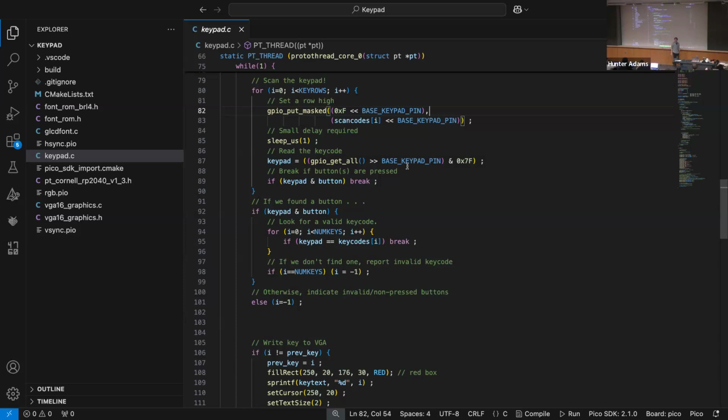So those of you that have run the keypad demo code, you will know that all that keypad demo code is doing is printing out the value of the key that's being pressed. It's actually reporting the value of that key via 2 media. It's putting it to the VGA screen, and it's also printing out via the serial monitor. You don't need to hook up the VGA screen, right? You could if you want to. We're certainly going to in Lab 2. But just for purposes of checking your keypad connections, you could just hook up the serial monitor.